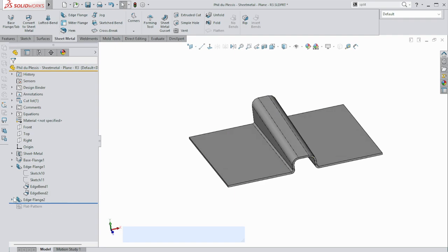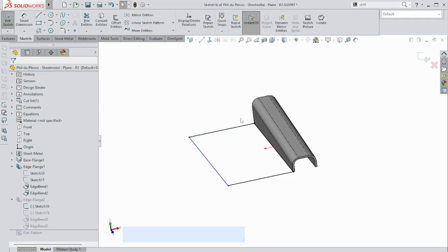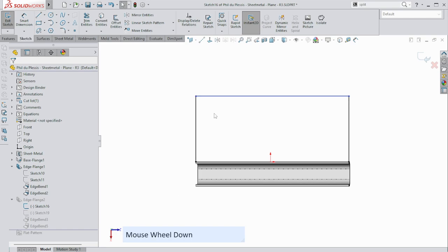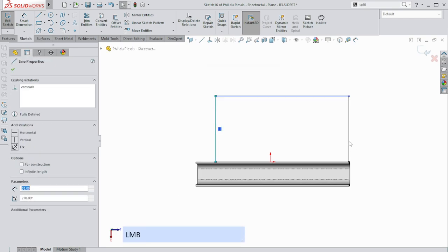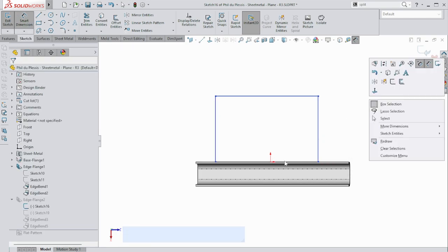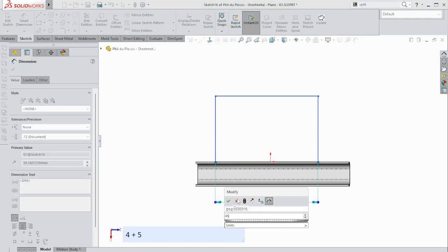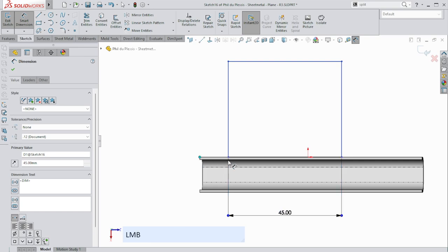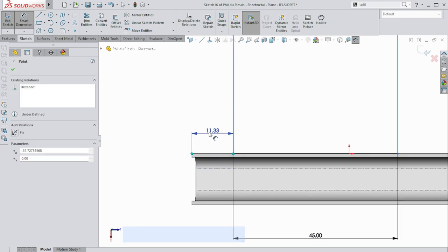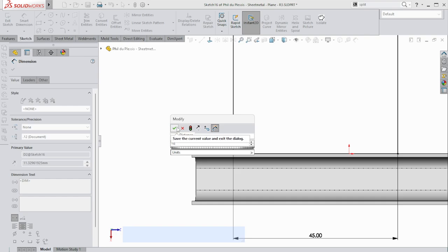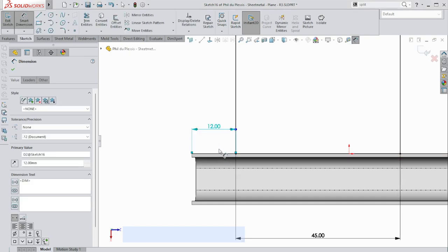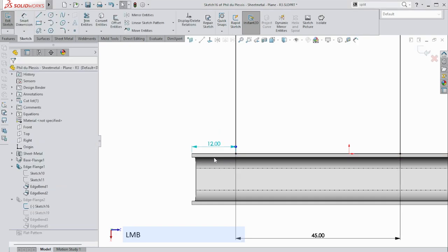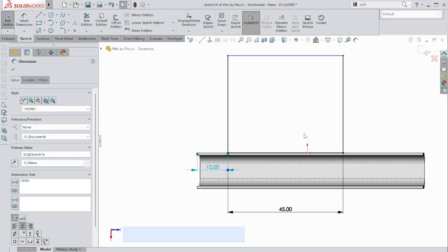Okay, so here's another neat feature. If you've got 2 flanges which are on the same plane, you can use one part of the sketch to control the other half. So here's my first sketch. Let's go normal 2. I want to pull this in a bit and pull that in a bit, and then this is going to be my wing, so I'm going to control the edge bend. I'm going to control both its width and how far away it is from the front end, because I want to be able to either put a wheel in there or to put in a fillet just to make it look like the fuselage is bending up, curving up.